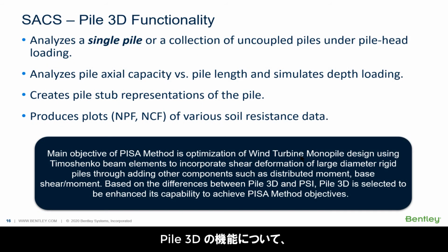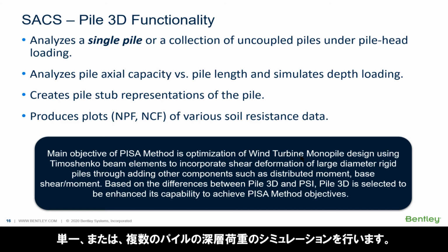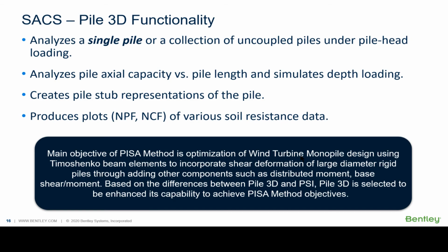As regards the functionality of Pi3D, it analyzes the pile axial capacity versus the pile length and simulates the depth loading of a single pile or collection of piles, but without linear structure above. It uses the finite element method, and the piles are represented as a Timoshenko beam. This is in line with the PISA method.